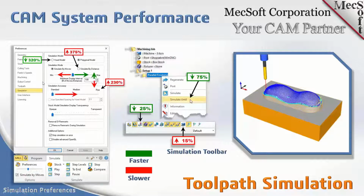Let me jump in here, Don. Okay. So the voxel model, there was a question by one of our attendees who's asking, what is a voxel model? It's a good question. Everybody's heard of pixel, right? Pixels are basically picture cells on your TV or your computer monitor. Very similar to that, internally in the CAM system, instead of just pixels, we actually create volume cells. These are dots on the screen, but they also have a Z depth associated with them. So we call them voxels, similar to pixels.